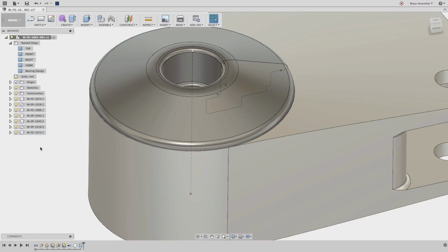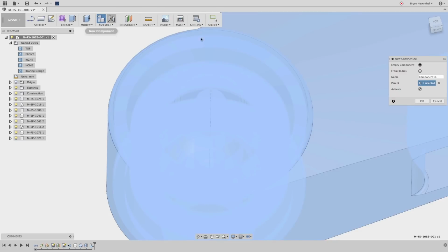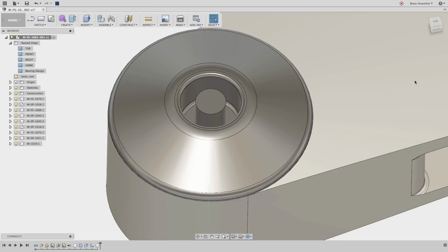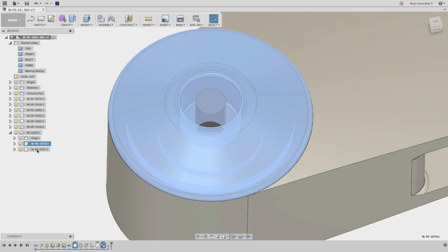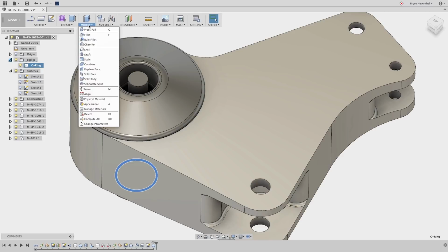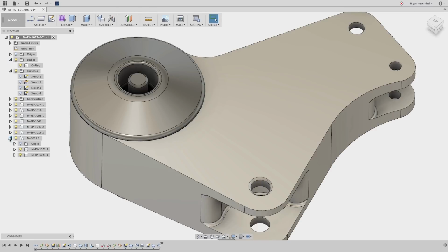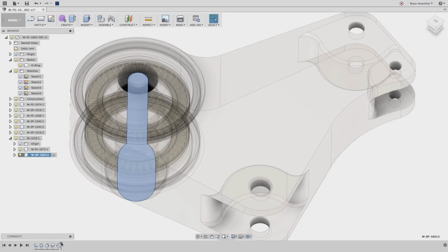Next, let's model another component. Again, referencing geometry between components is fluid and efficient. But what happens when you decide that this component really needs to be two parts that make up a sub-assembly? It's simply not an issue with Fusion 360. Make components at the point in the design that's most appropriate, and the structure takes care of itself. Sketches, bodies, components, and sub-assemblies can all live within the same design. And don't worry about placing features on components at the wrong level of an assembly, even though this component was not set as active. Fusion 360 associated the feature to the component automatically.